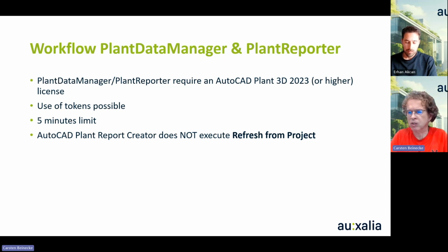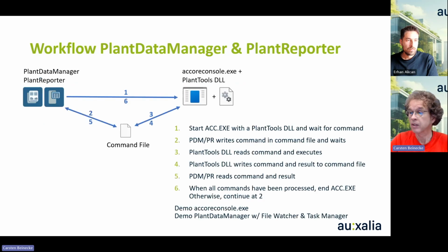Also, a side note: with the AutoCAD Plant Report Creator, you can create lists or reports with your collaboration project, but you need to start Plant 3D first and open the project to have the latest data in your work folder, and then you can use Report Creator to create a list. With Plant Reporter, this is not necessary.